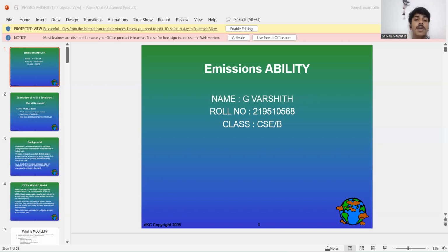After IM repair, emission level of OBD failures is assumed to be 1.5 times the FTP standard, with no change over time or mileage. Phase-in of IM240 versus phase-in of IM25/25 for 1988 to 1993. You can see the diagram.